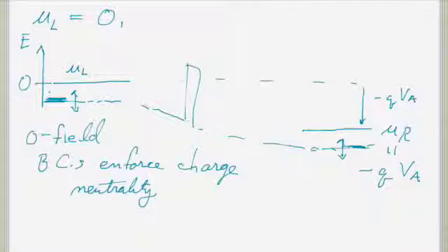if you make your lead regions far enough, so physically your fields are decaying throughout the whole device region, you're going to get pretty much the same answer to within numerical accuracy. You'll just get a little funky stuff at the ends that is different, and if you use your eta and all these generalized boundary conditions, what's going on at the very end of your simulation domain doesn't matter. But these are much nicer. And that's what we use.